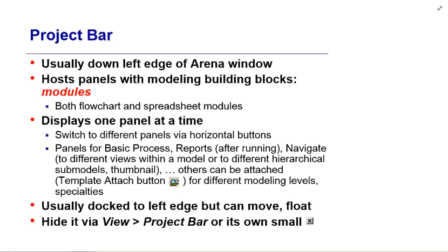The adjustable batch, haven't done anything with that yet. We'll get to that later probably. The record module is an important one as well, and that's for recording data. So if there's a specific piece of data that you want to capture that's not part of the normal reports that Arena has, you can do that through the record module, and then it will show up in your reports as a user specified characteristic. So that can be helpful as well.